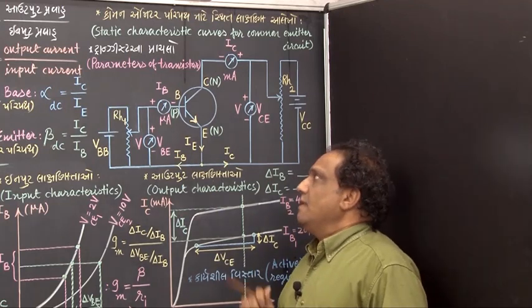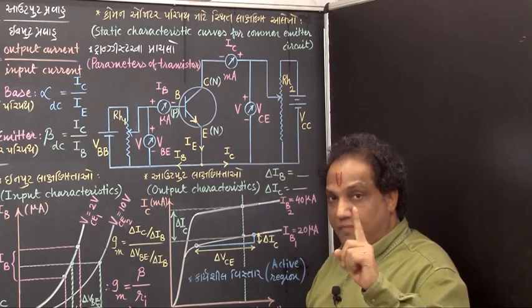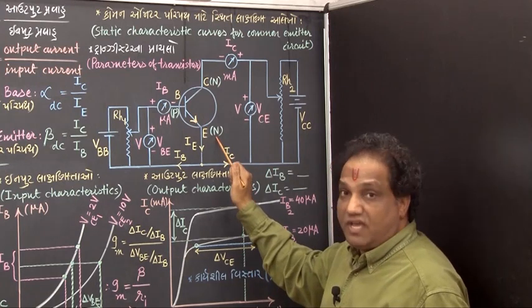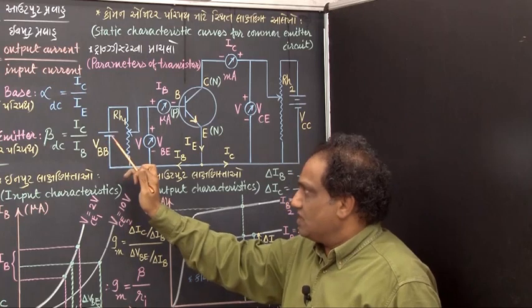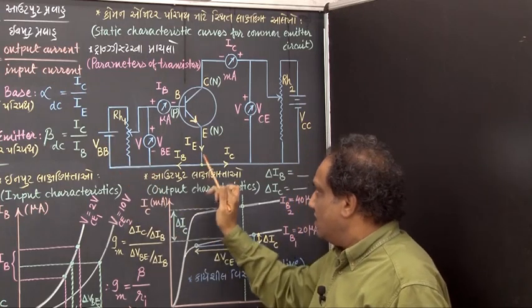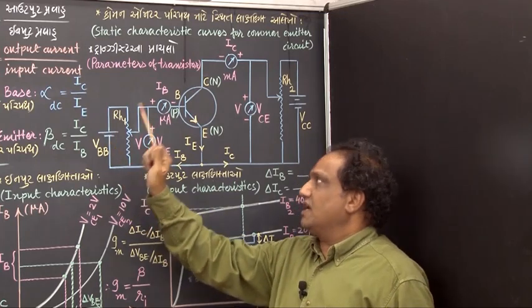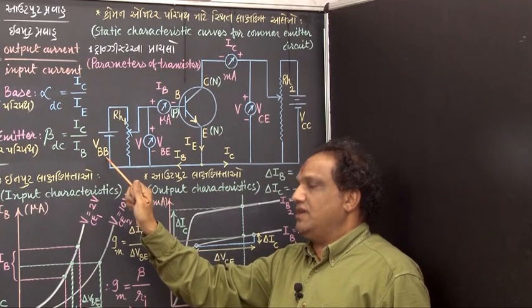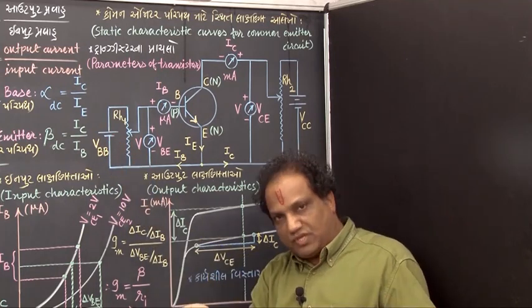Look, first of all, tell me, with emitter, what do we require? Emitter junction is to be given forward bias. So, N with negative. For that we just take one battery whose negative terminal is connected with the emitter. And this is the battery which is connected with base. So, its EMF is shown by symbol VBB. If lower terminal is negative, naturally upper terminal will be positive.